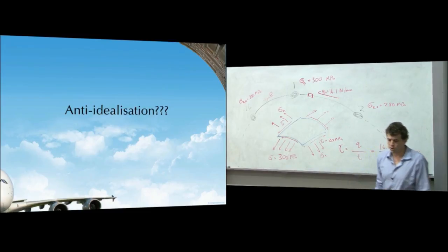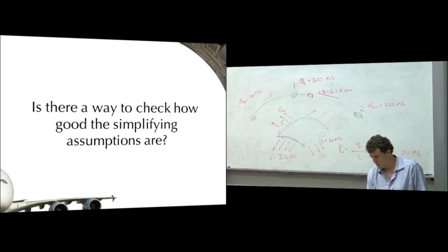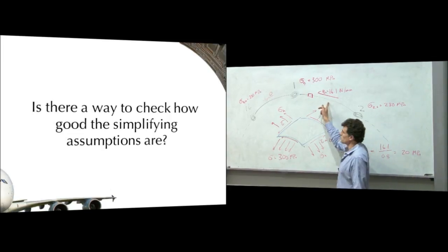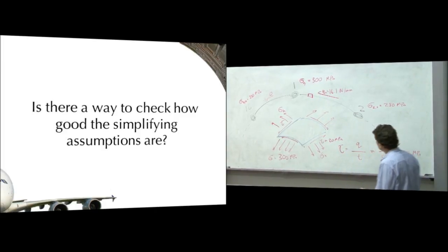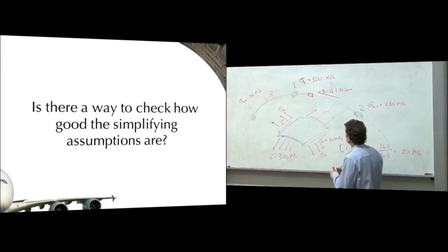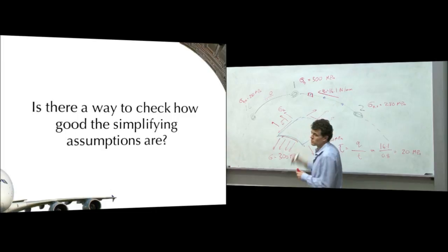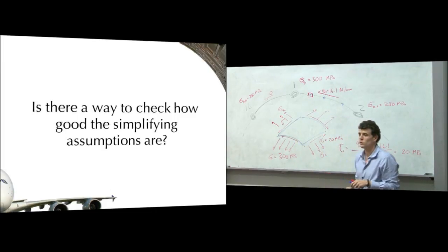It's not an easy thing to do the interpolation because the stiffeners are going to affect our calculations quite a bit. So what I want you to have a think about before doing the assignment is, is there a good way of checking whether our assumption that the shear flow in here is constant is a safe assumption? One way that we could do it is potentially to add some more booms and then work out how the shear flow varies between all those booms.